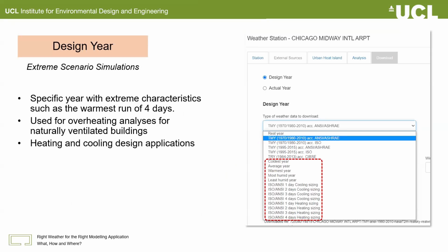Overheating assessment is complex, and weather files being used may change depending on the overheating calculation methodology. For example, overheating calculation required by CIBSE have a specific design summer year file, DSY file, for future. These are specifically created for overheating studies and have long hot summers to account for what might happen in future, but the winter weather data in those files is not projected for the future. Therefore, those files should not be used for annual simulations for future climate.